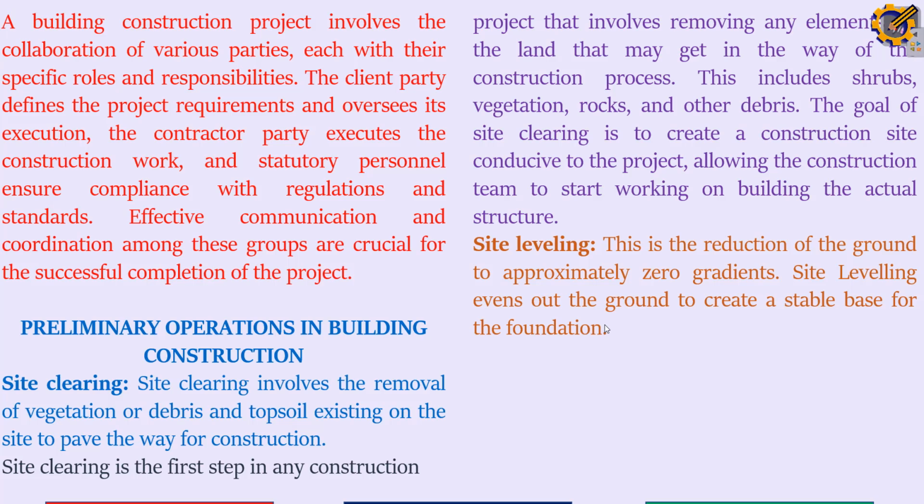All right, but in case the gradient or the slope is very much, then there is a way in which a foundation can actually be erected there. There is this thing we call stepped foundation. In such cases, stepped foundation will be employed. So if the slope is too much, maybe 10, 15, 30 degrees, you get this grade of that area, you just employ stepped foundation in such a scenario. So that's that about that.